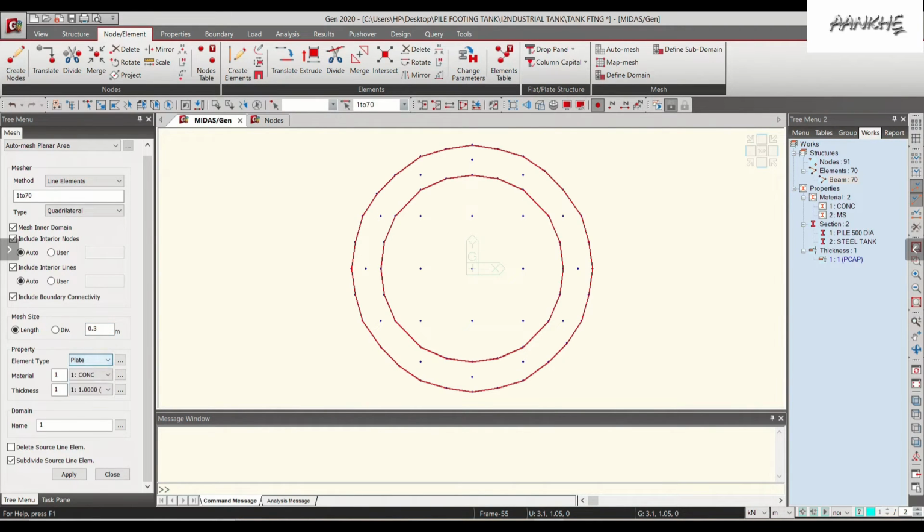It is capable of bending. Like here, it is plane stress, which means it can only take its load in its plane. In the outer plane it cannot take load. But a pile cap is a rigid plate, it can take outer plane loads. Plane strain, something like a very long retaining wall, is termed as plane strain. It will be more elaborate in the FEM chapters. And axisymmetric means a cone type, shell type, or a chimney can be termed as axisymmetric. Here nothing works except plate.